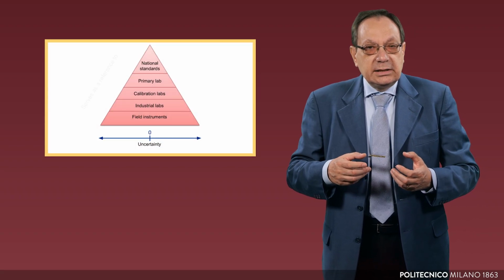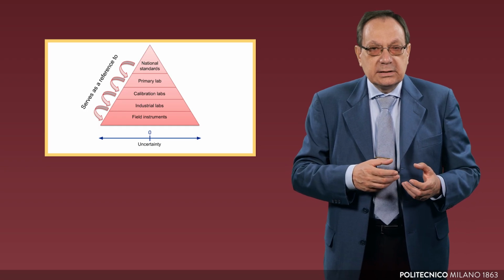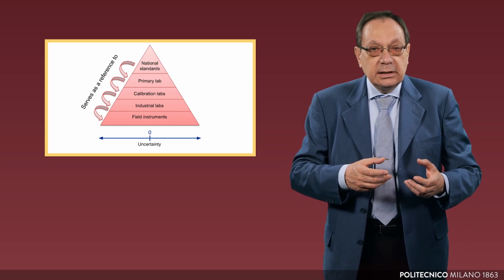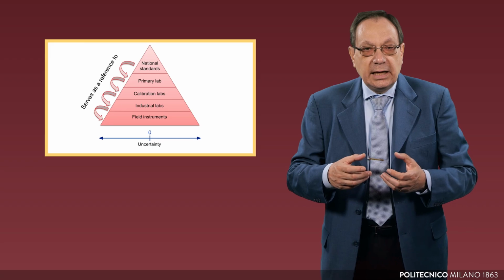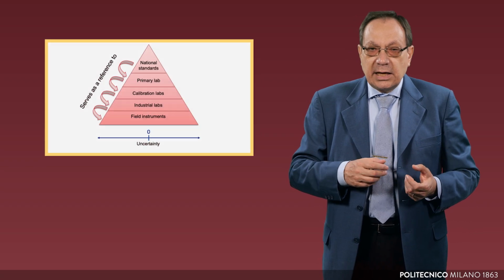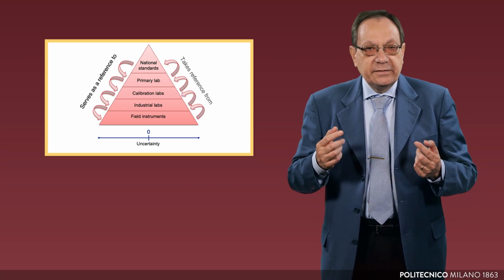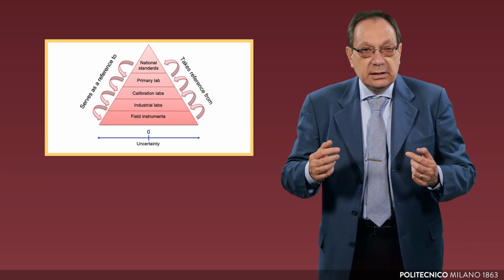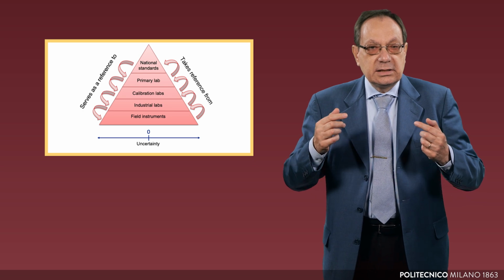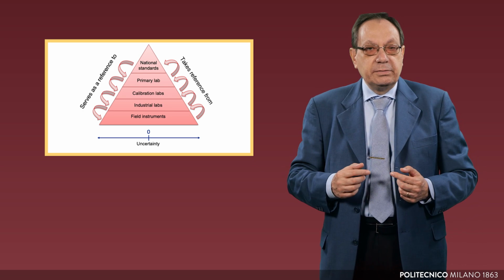Here we see that the higher levels serve as a reference for the lower ones. That is, the latter regard the instruments at these levels as measurement standards. In the same way, we see that the lower levels take their reference from the higher ones. That is, they regard the instruments at these levels as measurement standards to be used for their own calibration.